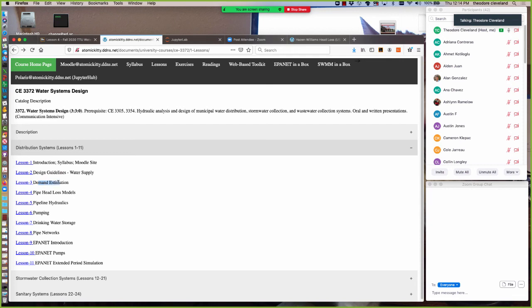We spent last time on demand estimation, and today we reviewed our fluid mechanics. The key points for today are the head loss models, Darcy-Weisbach and Hazen-Williams, which are by far the more common of the 3 for use in water systems. And Hazen-Williams is probably the most common, at least throughout the United States.